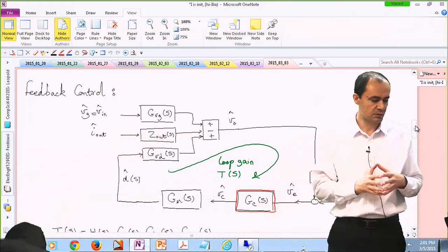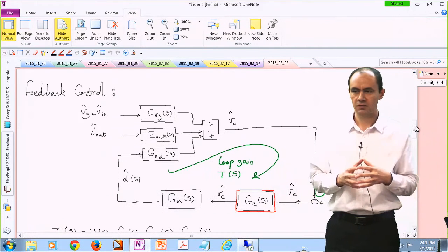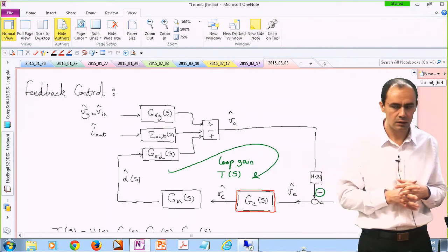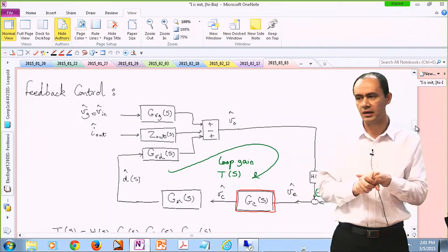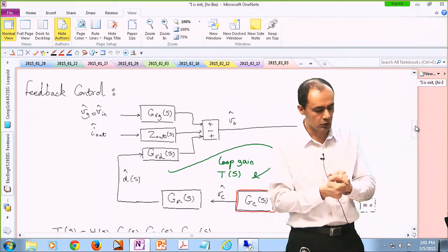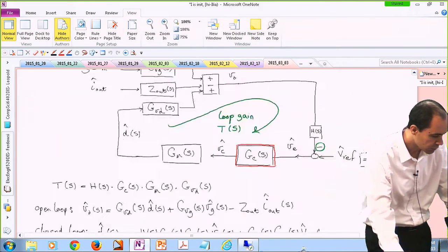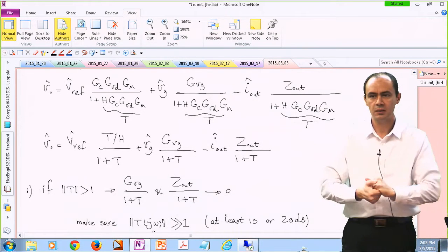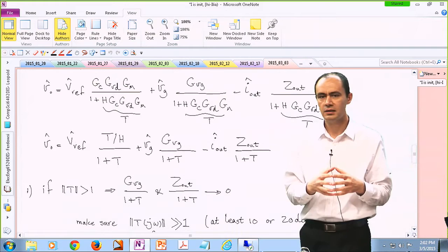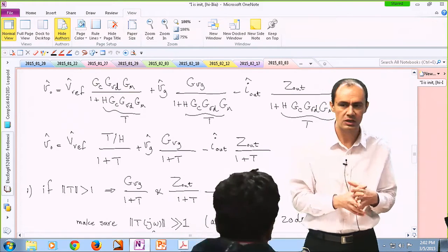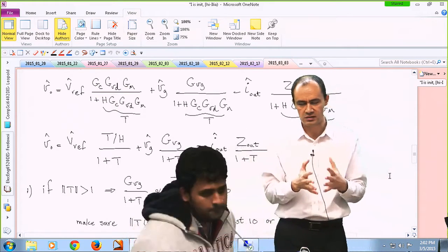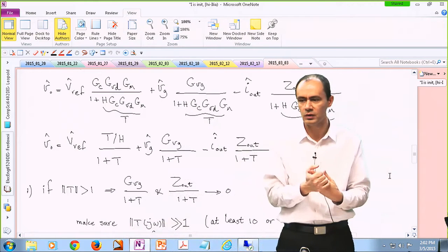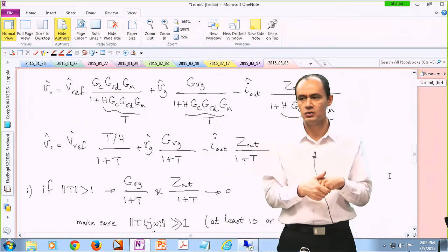So what we talked about last time was, if you look at our loop gain, the basic characteristics that we expect from it. For instance, our loop gain should be very large at frequencies where we have dominating undesired harmonics, for instance, in the input voltage. Like, for instance, you are trying to rectify the power from the outlet. There's 120 hertz ripple in that, and then you're feeding that to a DC-DC converter.